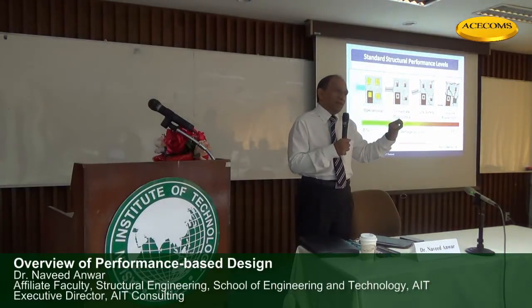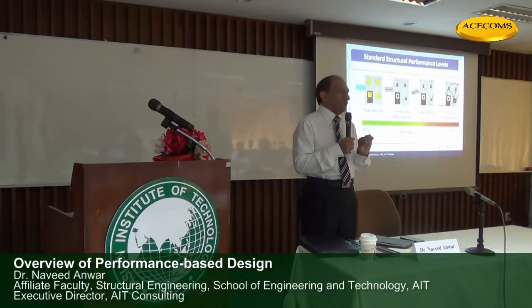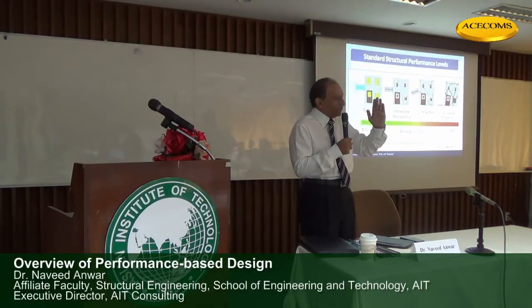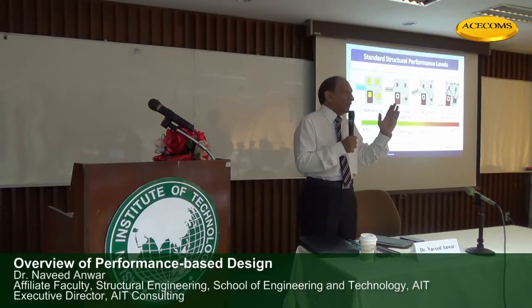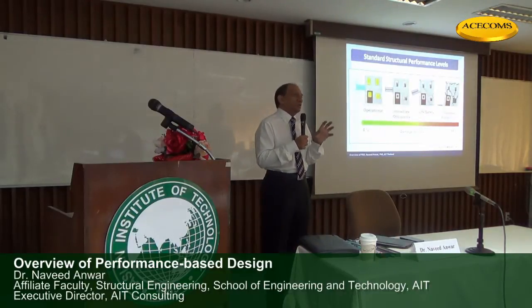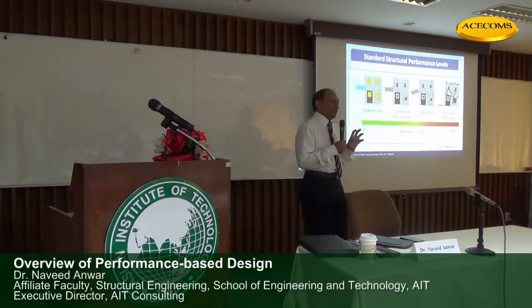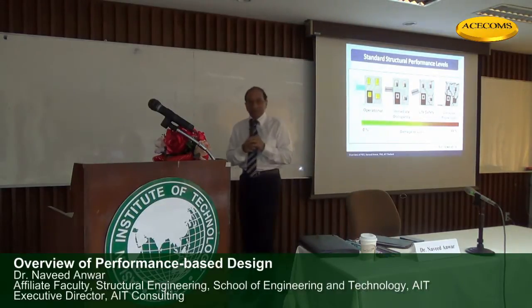We only care what the deformation will be and try to limit those, because collapse happens because something bends too much, not because the bending moment is too high. Something can bend at a small bending moment also. Another member may not bend at all even for a large bending moment. So the bending moment itself has no measure into the collapse. It is the deformation because of the actions. So we limit ourselves to the deformations.